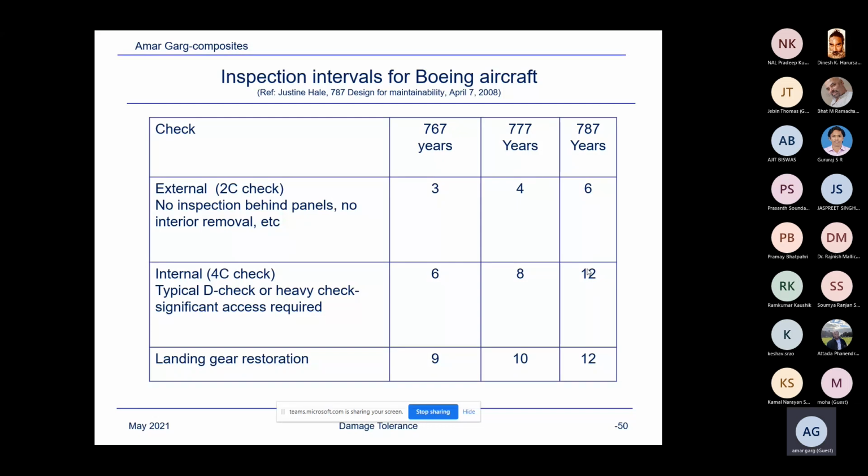Airlines would just believe Boeing that they don't have to do anything for 12 years unless something is visible outside, or a malfunction of some detail, some failures. Otherwise, detailed inspection will not be done. Detailed inspections are very expensive for an airline.